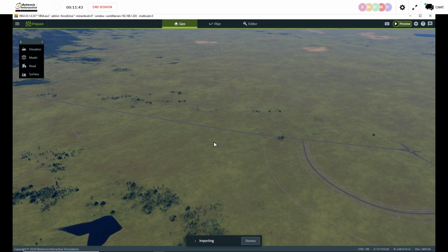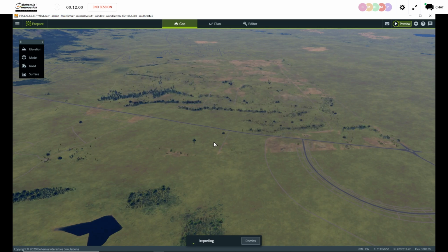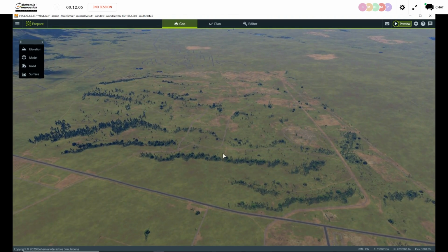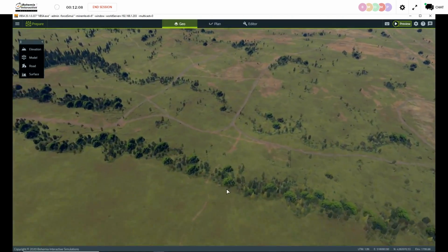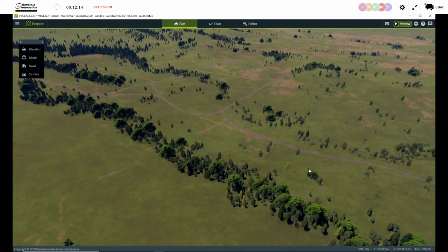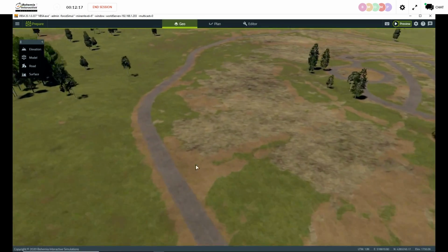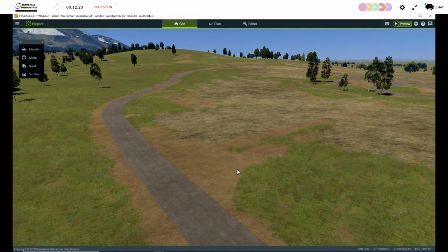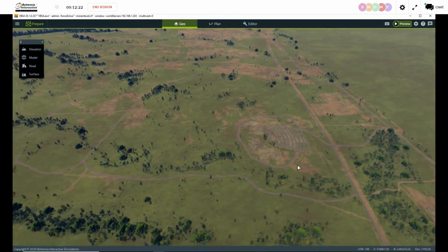So surface data really defines material textures and such. Using our tool TerraTools by VBSim, you can really do this quickly using a tool called Material Map. It looks at an image of an area and automatically figures out where the trees are, where the dirt is, and so on and so forth. So that's what you're about to see. And any GIS analyst or any GIS expert can do this kind of work. So really quickly there, you can see that we've just imported an improved surface definition. So we've got some more fidelity in where our trees are. You can see here that we've got some dirt and some areas where buildings will also be imported in. So that's our surface data.